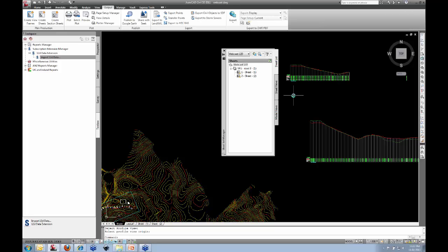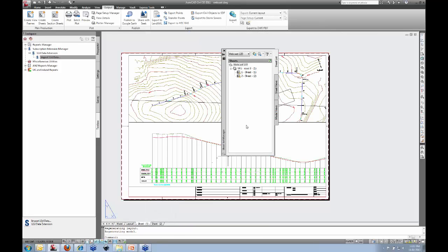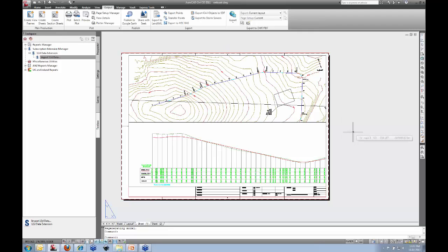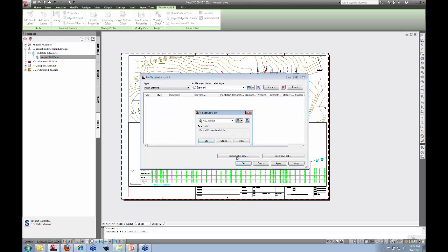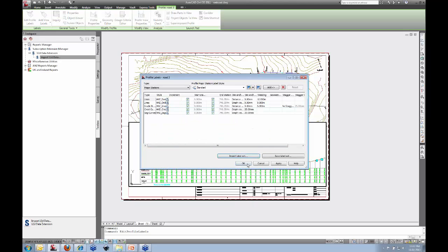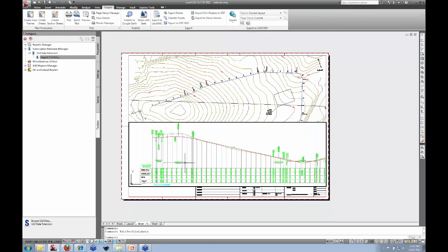So it takes away all the grunt work in doing that, automates it for you. You now go to your tabs. You see Sheet 1 here. Let me just close the Sheet Set view. And all those labels, everything shows up as expected. At this stage, you can come in here and double-click. You can select that profile and do whatever you want with the labels. So let's select for this one. Let's put in the default view, which puts labels all over here.